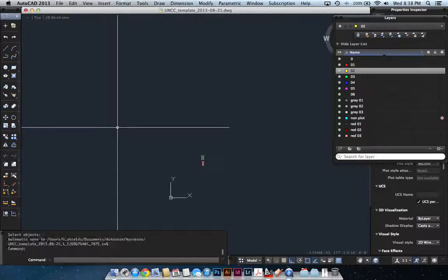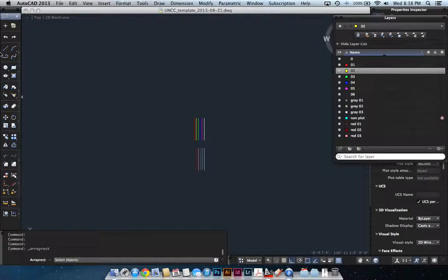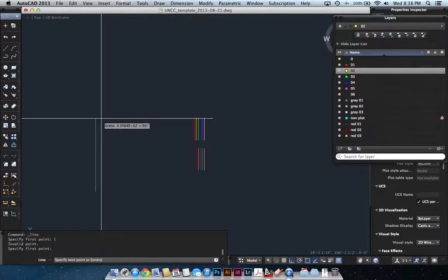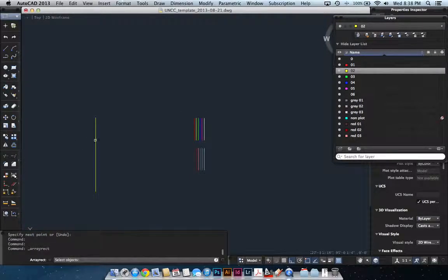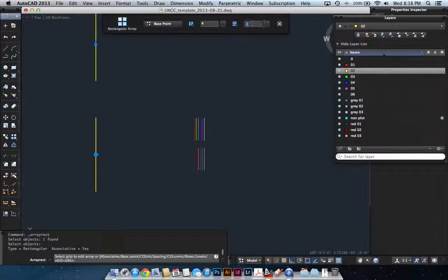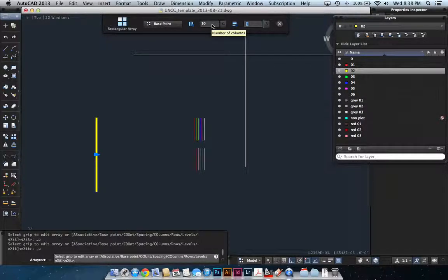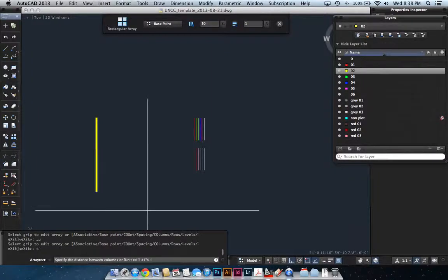So with those, you actually end up seeing the wide variety that exists between offsetting individually versus the array. I believe it's as simple as now using the array tool, sorry, I'm using here. And I'm at 4 columns. And I'll make it instead, actually I'll make it 10. And I'm going to make the spacing, we'll make it 24 inches.